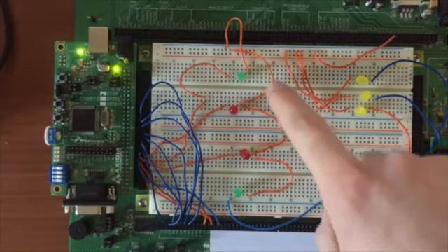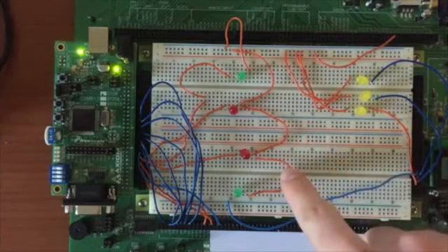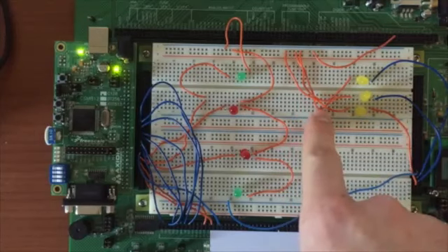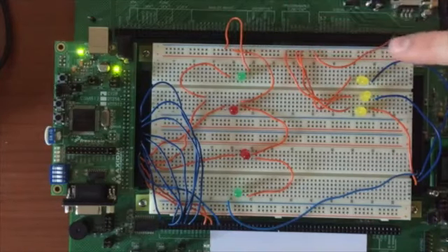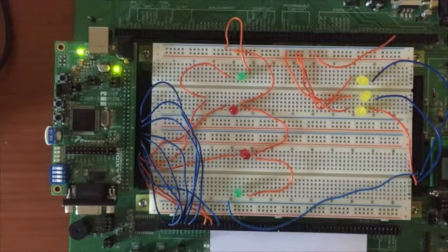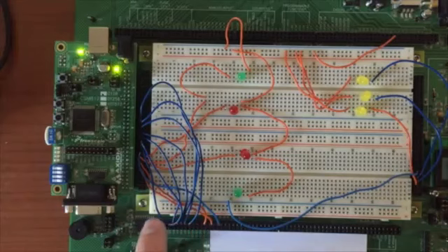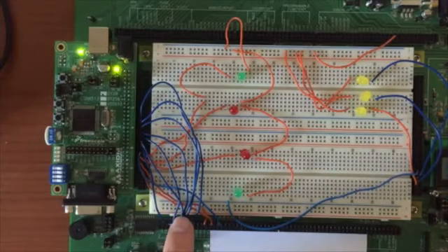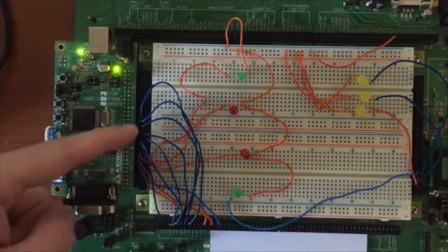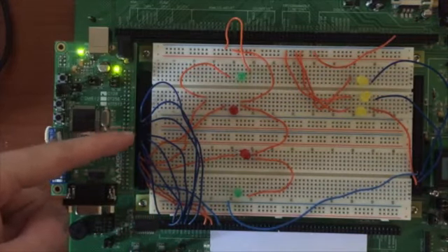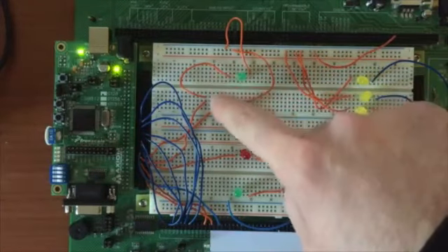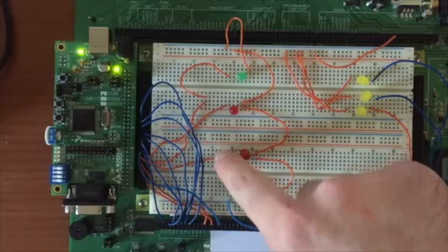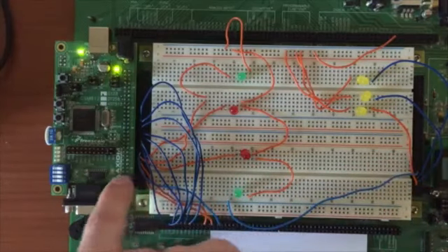We start down the centre where a common ground has been constructed. It leads up to that top bar and feeds into the ground on the board. As you can see, on the bottom left, the buttons are connected to our designated input, port A. The output from the microprocessor was allocated to ports B and E. As you can see, all the LEDs on the board are fed from these 2 ports.